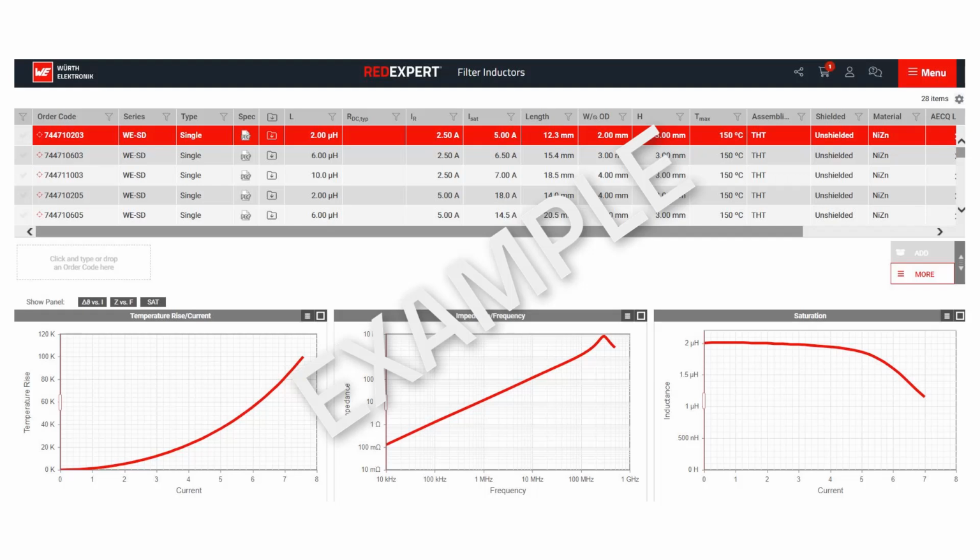You can make a filter for the current which you need. You can put all your data in the parameters, where you want to know exactly which inductance value you need according to your duty cycle and switching frequency. And if you keep the ripple current not higher than 30-40%, you may have quite a good solution.